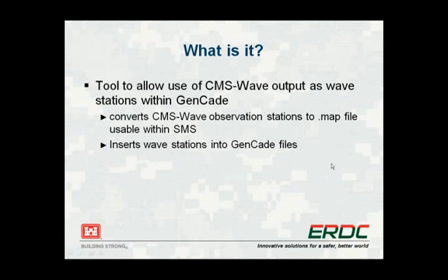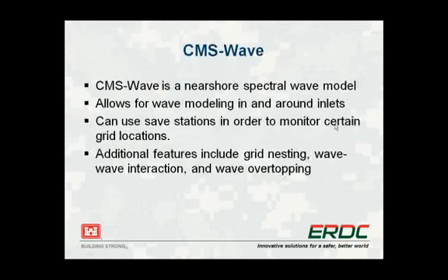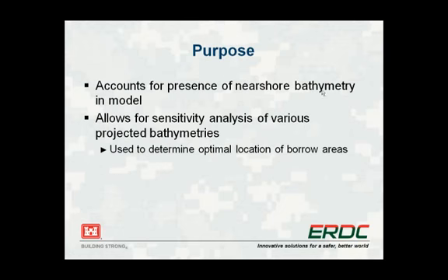Once again, the tool converts CMS Wave observation stations to .map files usable within SMS, and inserts wave stations. The purpose of this is it accounts for the presence of nearshore bathymetry in the model. It allows you to compare different bathymetries if you're building an offshore berm, or if you're doing a dredging project, you can determine if the bar areas are in the best location possible.